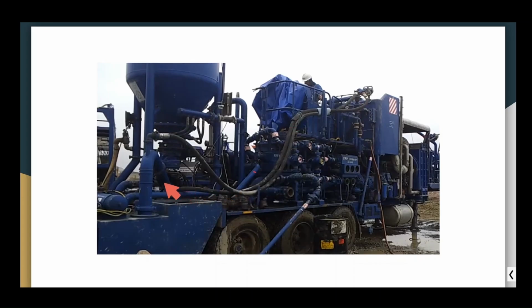One line goes directly to the knife gate, and this is a water supply line, and this additional water supply line stimulates better knife gate hydraulic driving. So I can open or close it where I want, and then by gravity and by the effect of Venturi, the dry blend cement flows here, and then water shears it, and we can produce our cement slurry here and start the mixing process.